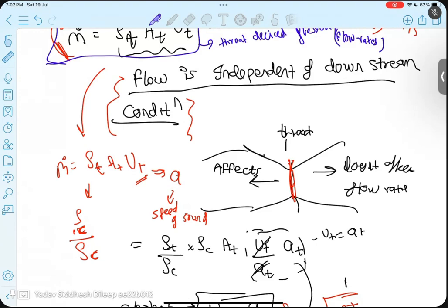That is why we are taking the throat, because after the throat, I told you, take whatever, it won't affect the upstream condition. That is why I always take the condition of the throat, because the throat is the last condition that can affect C star, and we always have everything for the throat because the Mach number is 1. So things become simplified. Otherwise, at other places you don't know the Mach number. At the throat, you always know the Mach number. That is why we try to solve the assumption based calculation derivation. It gives efficiency. That is why we always talk about the efficiency of the rocket engine, but it at least gives you a very good place to design a rocket engine.